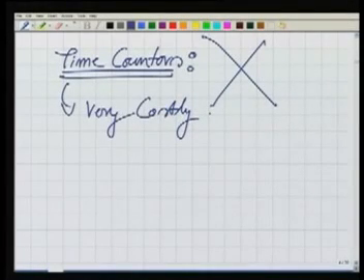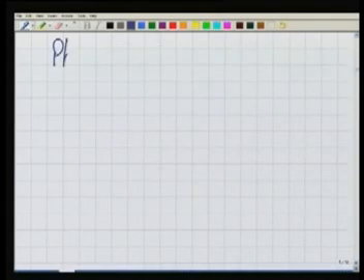Here in the land survey, we are looking for an instrument which is cheaper, which can be handled by many people. The cost is less. You can take it to the field. The size of the instrument should be small. So because of these reasons, generally the EDMIs which work with this time counter principle or time measurement are not used in land surveying. Rather, we use another principle, which is the phase measurement.